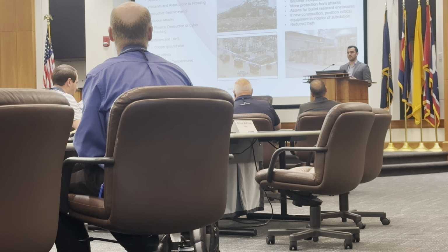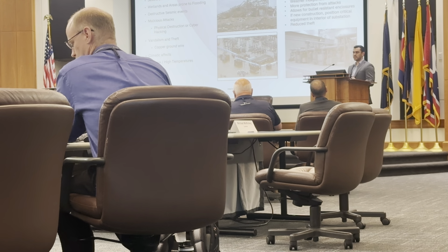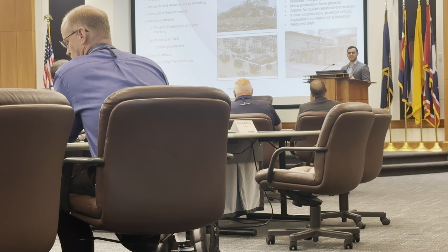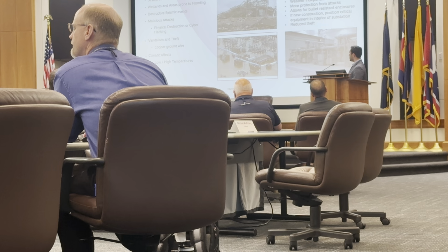We've seen those a lot in California, we've seen those a lot in the Central Coast. People here in the US have guns, and a lot of the time substations become an aiming field. So when you have a GIS inside a building, it mitigates that risk. And also high and low temperatures: high and low temperatures do not really affect equipment inside buildings.